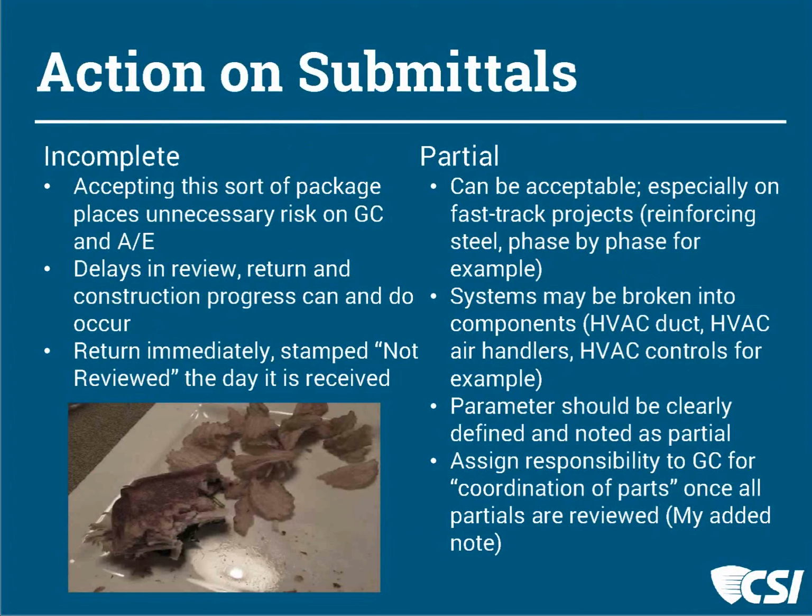Let's say paint as an example. And so I would make that judgment based on the information listed within the spec section itself. And I would tell them in my general conditions that we're going to review it, and if it's not complete based on the specifications, it would be returned. So I think you have that authority.